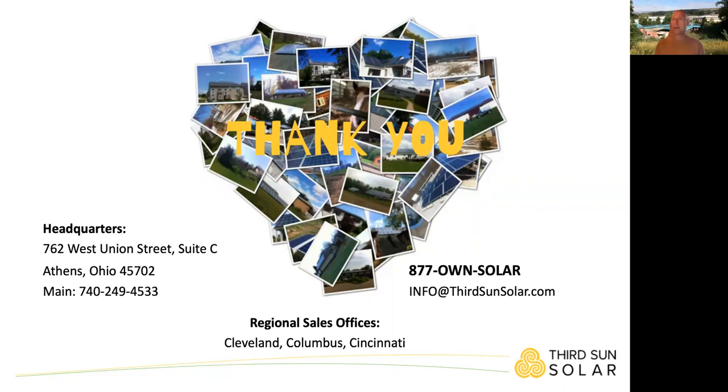And so the fine print is, are you going to get 80% of nameplate at year 25? Or are you going to get 92% as with the REC Alpha? Or is it maybe 86% as in some of the other products? So those are the fine print to evaluate over time. And we're not as concerned if you're using a tier 1 manufacturer.